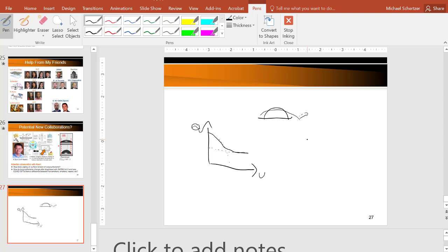Yeah. So we always need this surface energy to analyze our cutting process. Unfortunately, the energy estimated by the contact angle is always much smaller. I'd like to know the reason. Probably it is not a very accurate way. Yeah, well, it's tricky with contact angles, especially if you're using PDMS. PDMS has a reasonably high contact angle hysteresis, so it's really hard to measure the equilibrium contact angle, right?